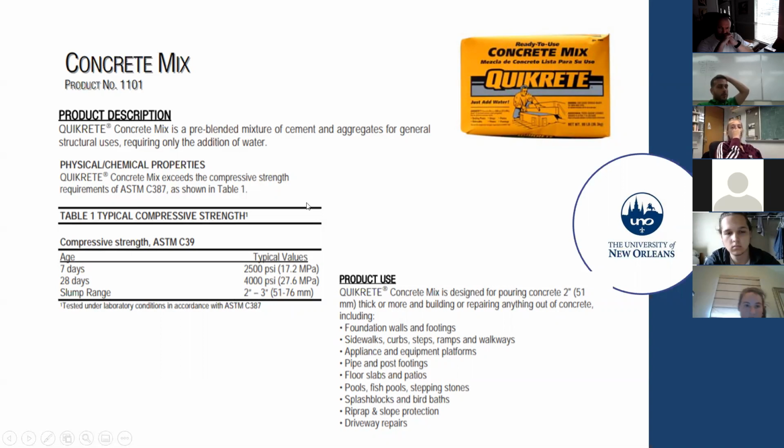Because what I do usually when our curing room is not working properly, I keep these cylinders right here, where the tap water is. And I keep adding water to the concrete sample while it's curing.